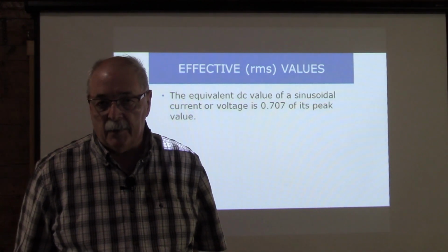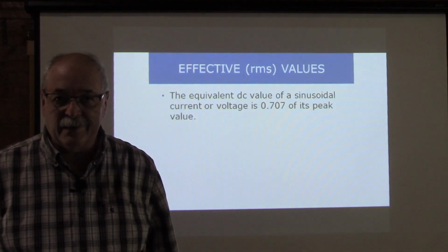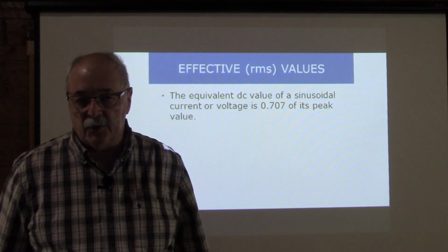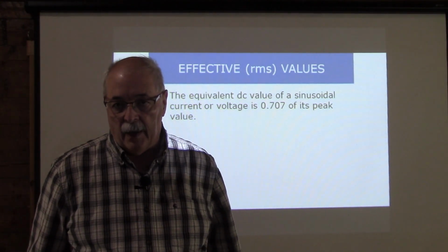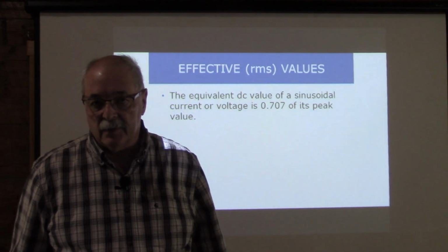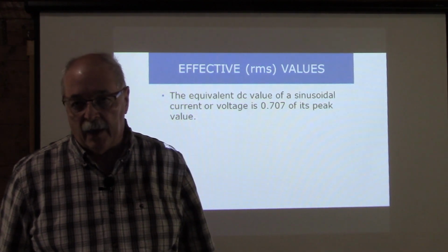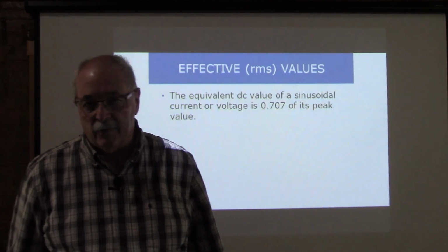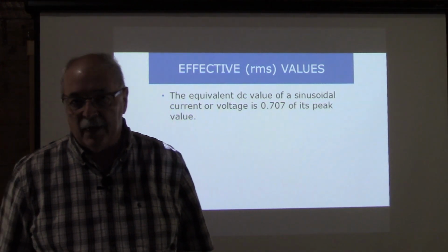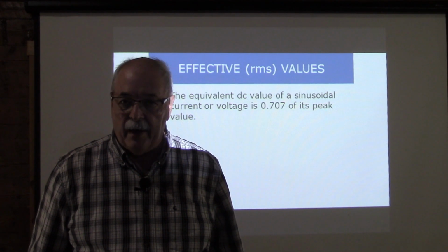So let's use that 170 number. Say you buy a sound system, it says 170 watts per channel peak, and it's really only putting out 120 watts RMS. But you're comparing it against something else that you're buying where it says 140 watts, and you say, well, it's less than the 170, but no, 140 was RMS. You have to keep that in mind.